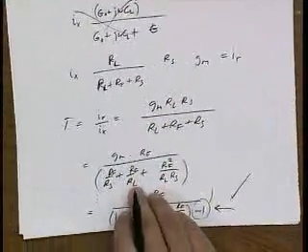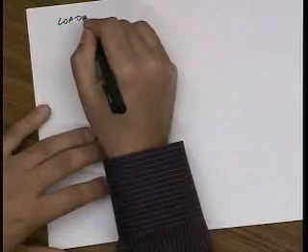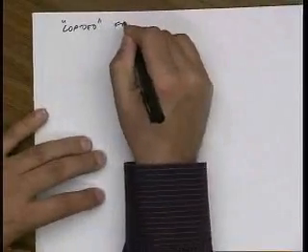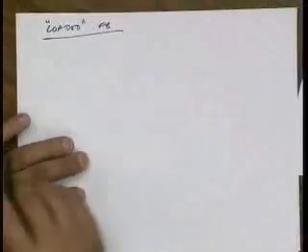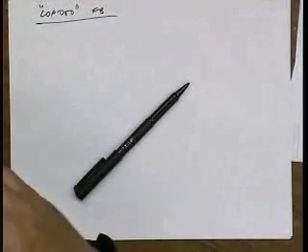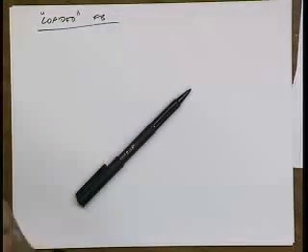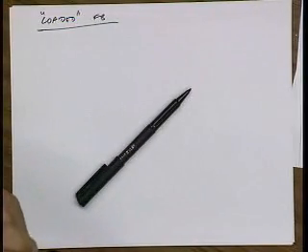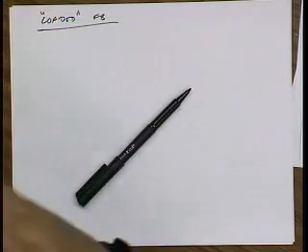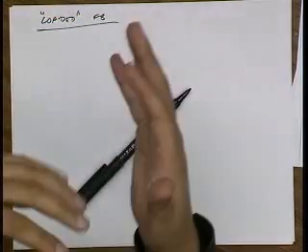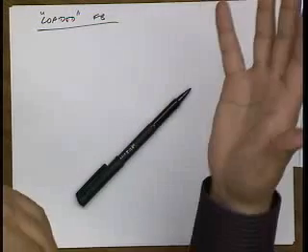Now I'd like to show you guys where this ideal feedback stuff comes from, or this loaded feedback. Again, I don't have a good name for it. The reason this loaded feedback analysis is useful is there are many cases where the feed-forward effects are not important, and with this approach you can quickly calculate the loop gain, the closed loop gain, and also the noise.